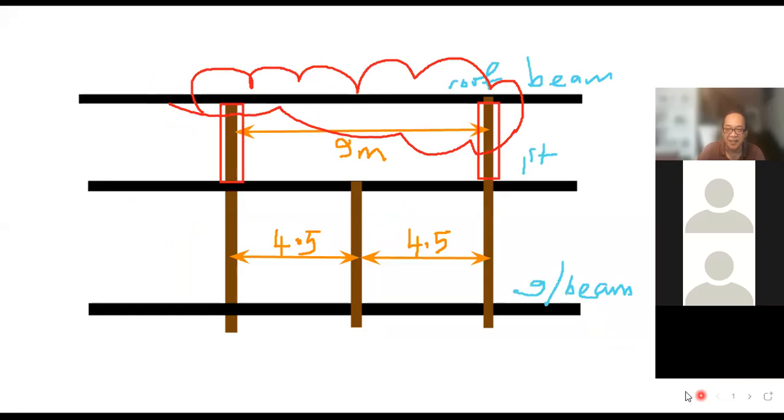At this particular position, the columns stop at first floor because of the constraint of the use of the classroom dekat atas ni. We cannot allow the columns to go up sampai roof level because of the restriction on the use of the classroom. If we allow this column to go up, then it will obstruct the view of students within the classroom, as shown dalam architectural drawing.